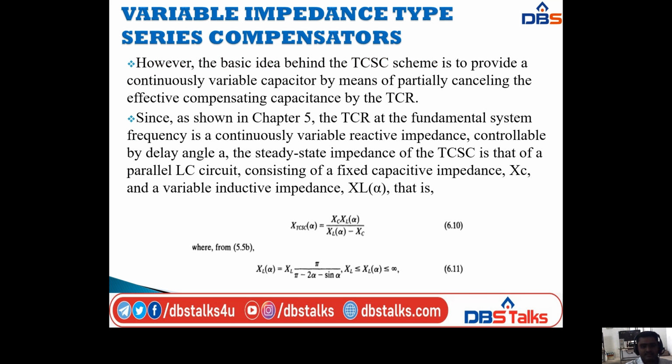However, the basic idea behind the TCSC scheme is to provide a continuously variable capacitor by means of partially cancelling the effective compensating capacitance by the TCR. This TCR was used in the previous chapter, in shunt compensation. So it is similar to the compensating capacitance of the TCR in the previous concept.